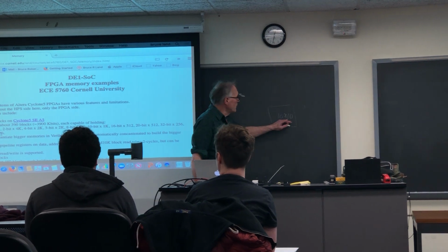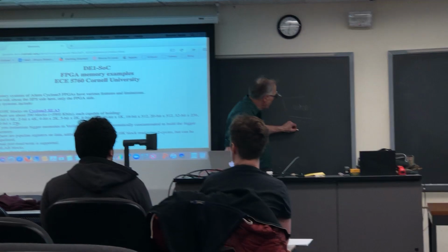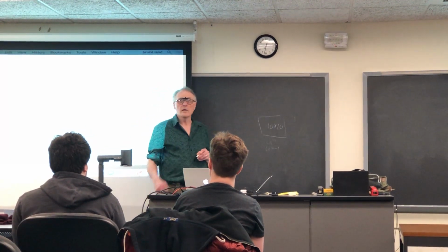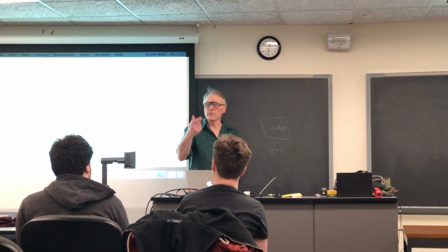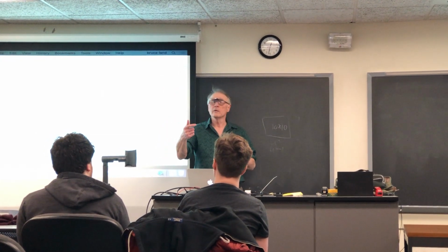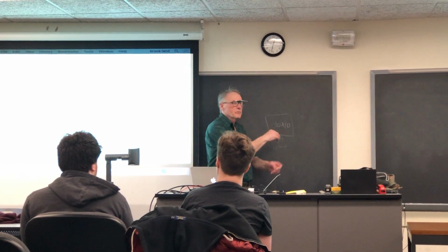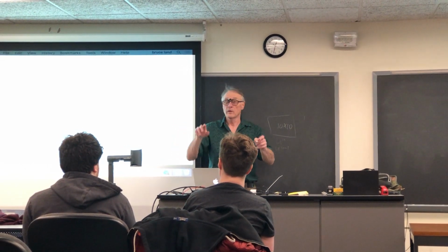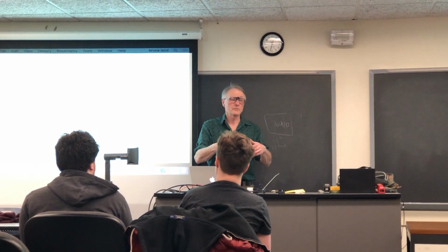So a 10 by 10 patch would store UN and UN minus 1 for all 100 nodes, as long as your state machine stepped through each node sequentially, read out UN and UN minus 1 plus the surrounding values, again sequentially read, did the operation, and stored back the result.